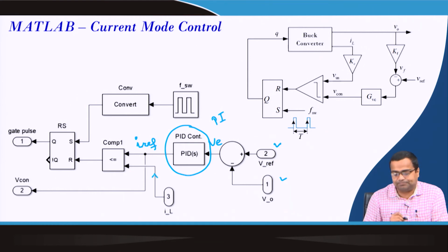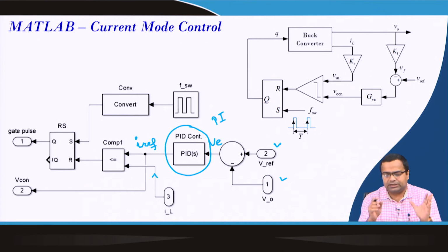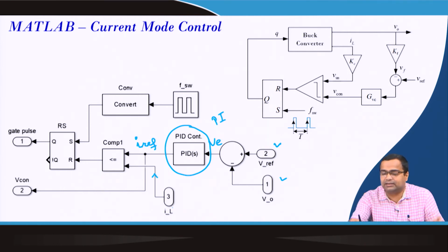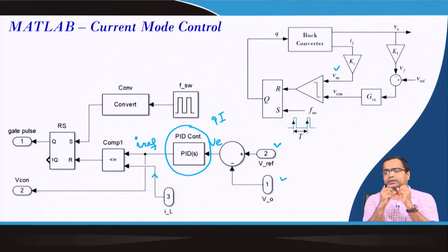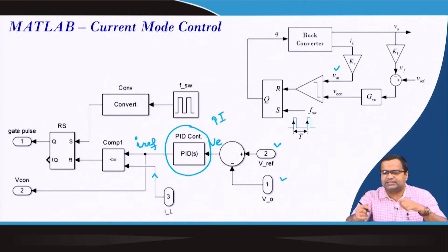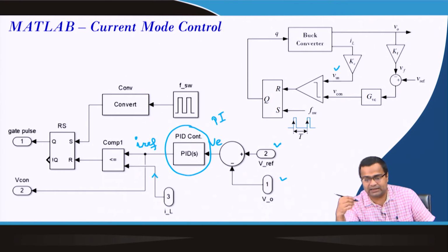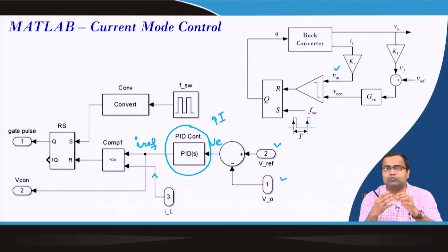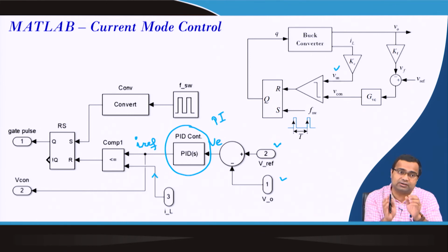the inductor current. In the last class we discussed inductor current sensing. That means typically the inductor current is sensed as a voltage equivalent to the inductor current, and this sense voltage is related to the current linearly with a scaling factor of R equivalent, and the magnitude of this R equivalent depends on whether you use a sense resistor, including the current sense amplifier gain.